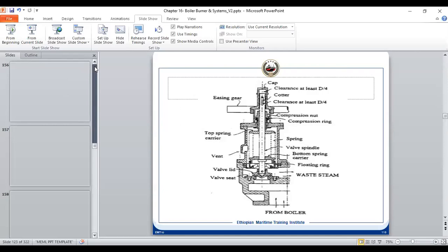normally all your IACS class. Of course, you obviously know what is IACS. All the major classification societies form a group which is called IACS. As per IACS rules, the periodicity of your boiler survey is normally 3 years, plus minus 6 months, but it is never minus. It's usually always plus, and they give the frequency as 3 years. You must have seen your class listing on board, depending on which class your vessel was classed with, whether ABS or Lloyd's or DNV, etc. All of them give 3 years.